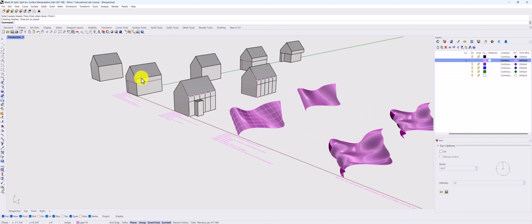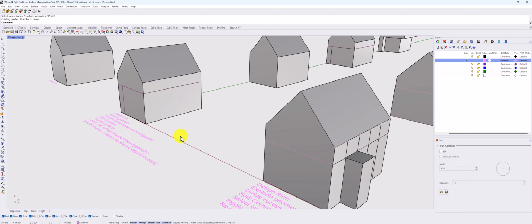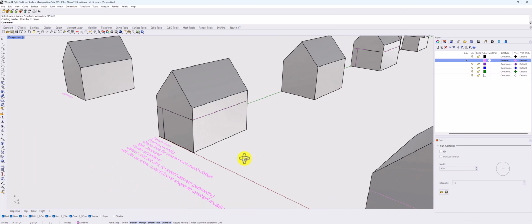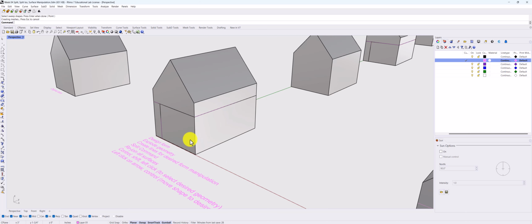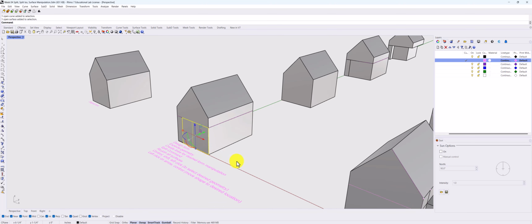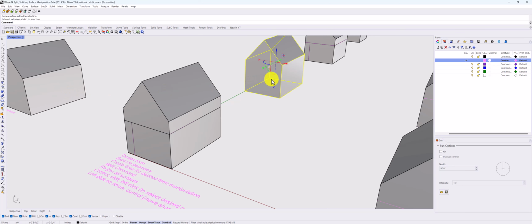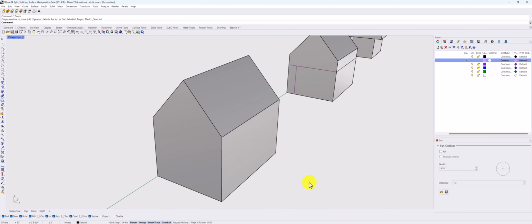And then the next option here is say I made my cute little house that we previously sheared to make oblique drawings. But I take my little house and maybe I want to start altering my shape. And so here I added some curves for maybe a head height and then a curve here. Technically I already split these using the split command, but let's go ahead and do that same.